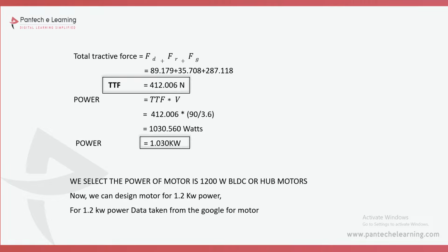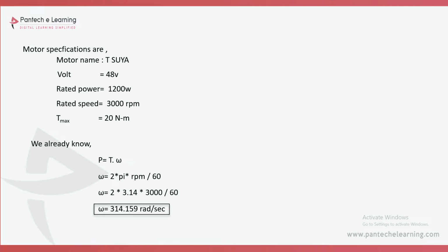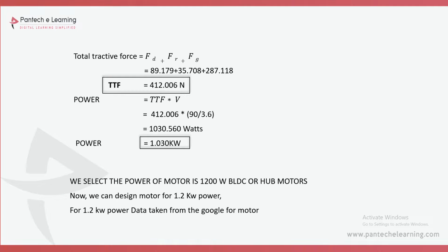Okay, so now I find the total tractive force. I take the sum of these forces, the aerodynamic drag force, rolling resistance and gradient resistance. The sum of these forces gives 4112 Newton. So our total tractive force is 4112 Newton.